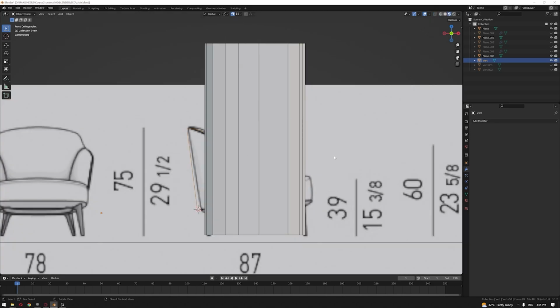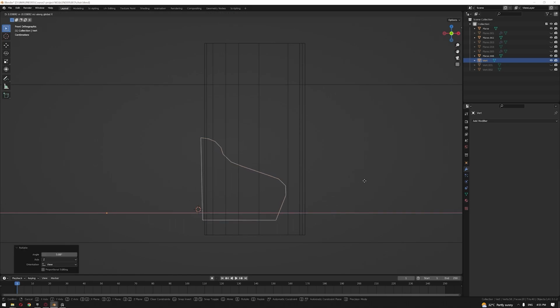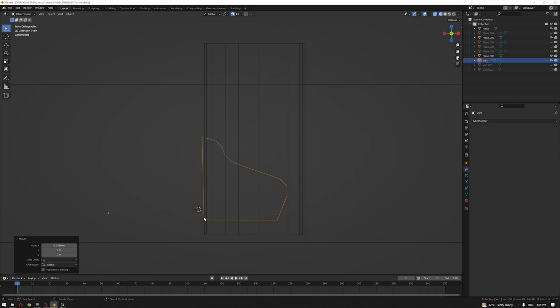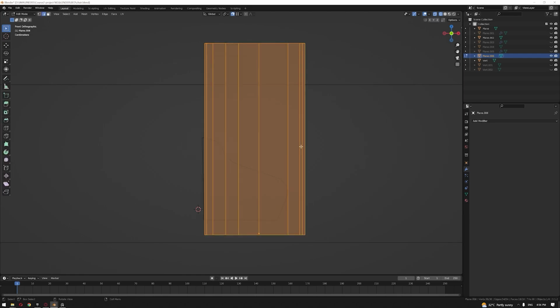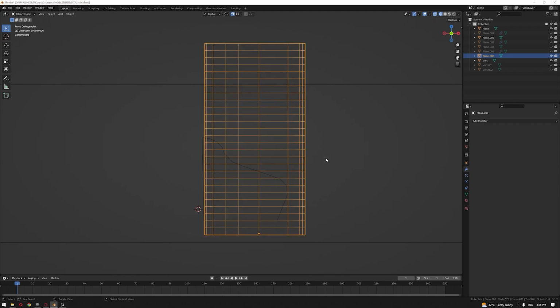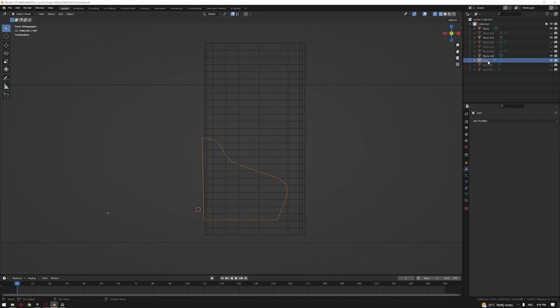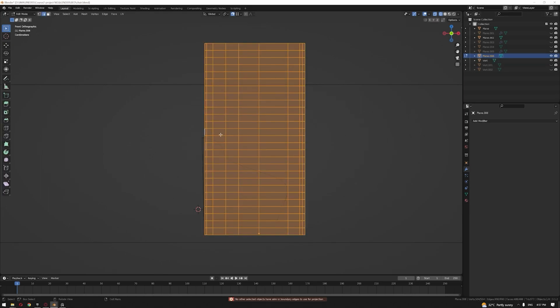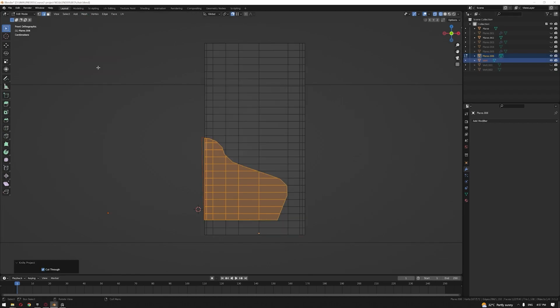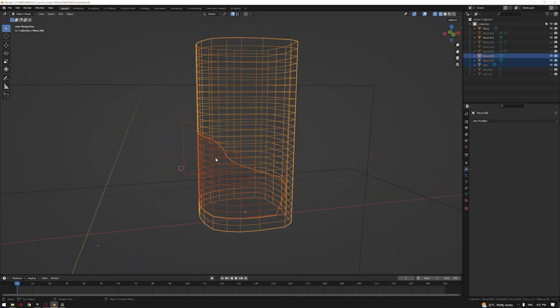Now, let's first make sure that we align our side shape horizontally, like that. Move it a little bit, but keep just a small amount of vertices coming outside the shape. Now in the front mode, let's also subdivide this as much as we can. So we want to get as many vertices as we can, and then select this, then Control-select the chair. If we cannot select it, just make sure which one it is in the outliner. Select all, then press Control and select the chair, mesh, knife project, make sure it's cut through, and then we're going to hit P to separate it.